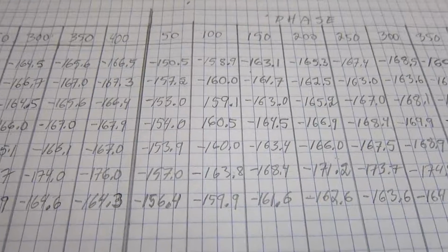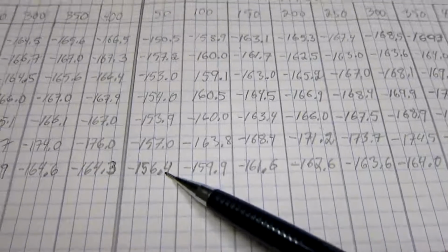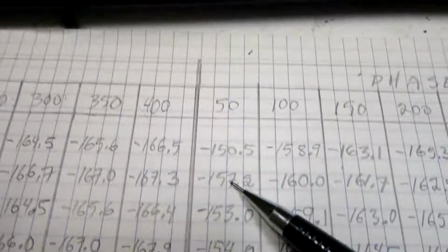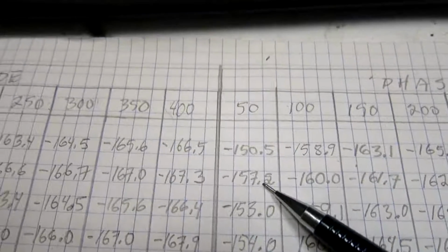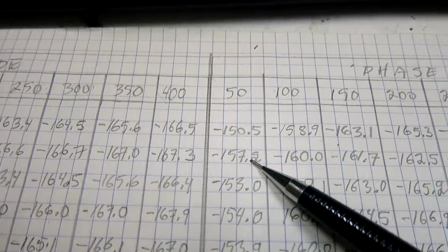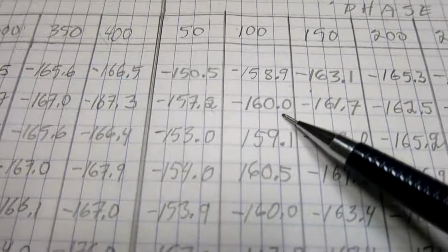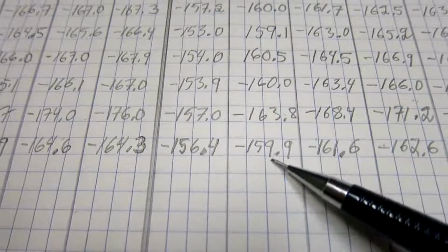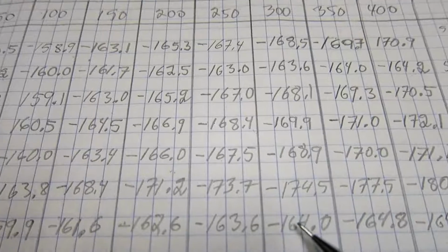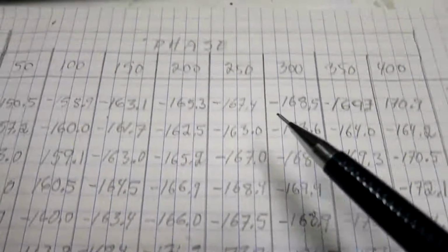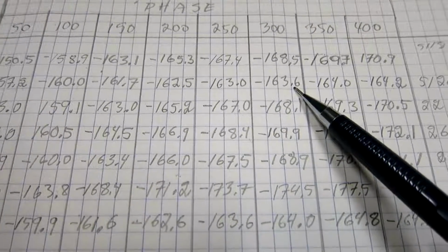What I can see is that the phase noise here, -156.4, is very close to the phase noise of the Wenzel oscillator at -157.2. I don't think this decimal is very significant, but if I go to 100 Hz, I get -160.0 and -159.9, and so on. The numbers are the same that I observe now and that I observed on the Wenzel. It differs here by 0.4 dB in the other direction.